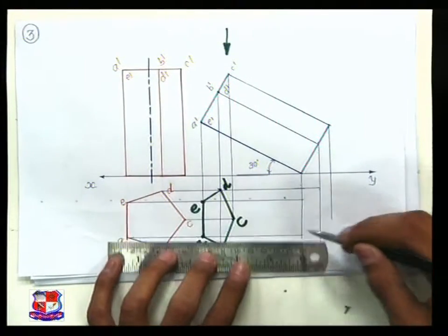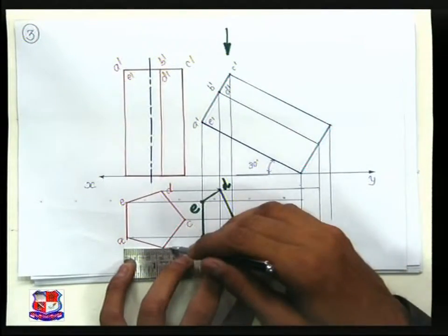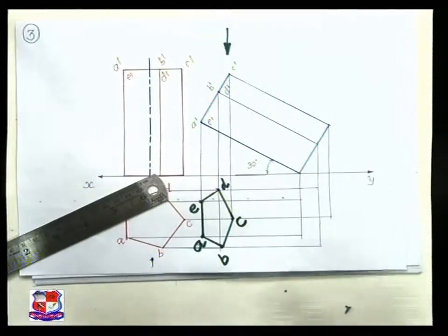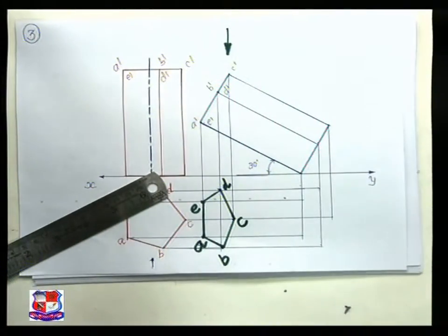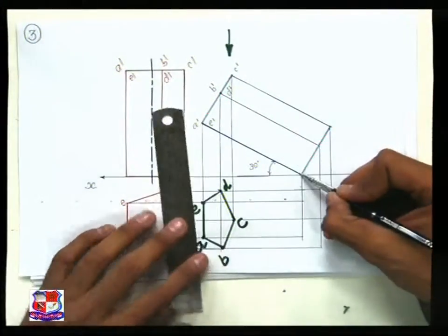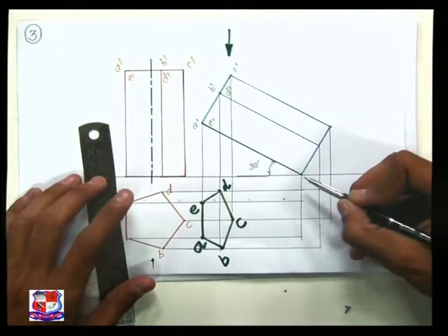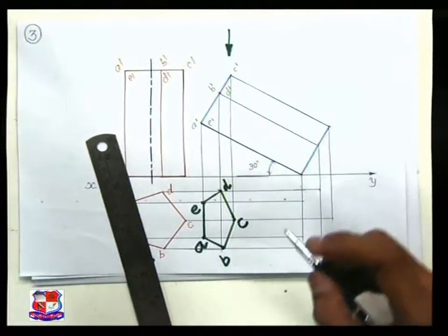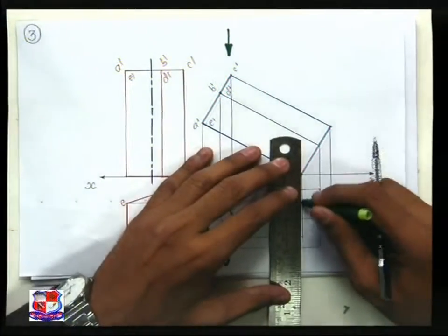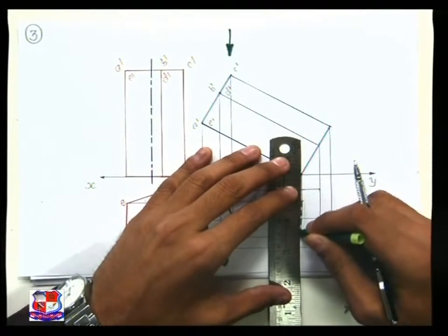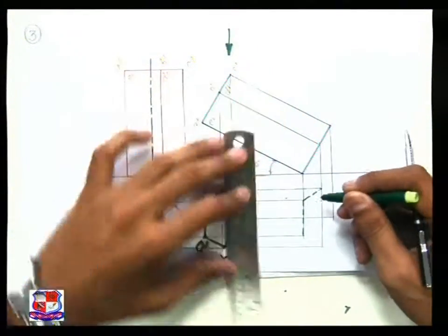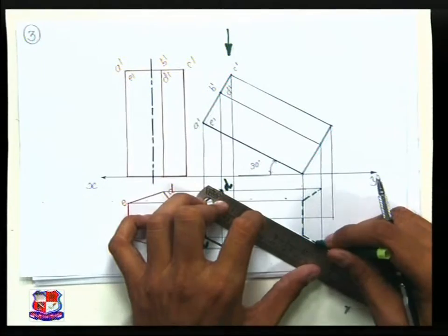Horizontal lines and vertical lines, that are also called projection lines, from the end points in the top view, and mark the appropriate points and join those points with the full line. But here, if we look from here, this corner is not visible, hence this corner point should be drawn with the dotted line. So join all these points which are towards the below side with dotted lines. So these corners should be drawn with the dotted line, and this also should be joined with the dotted line.